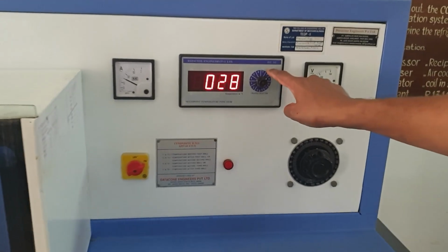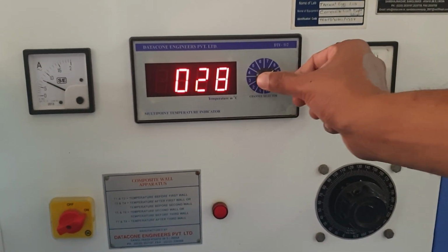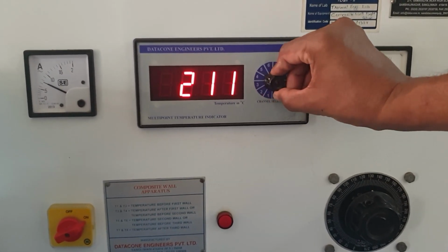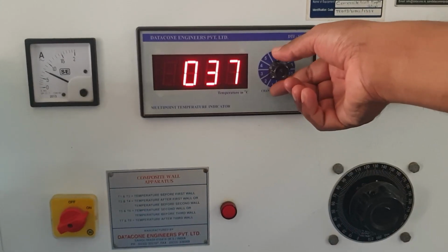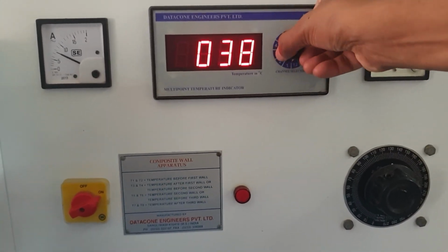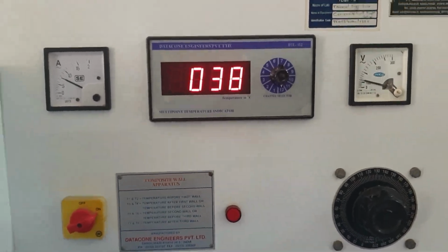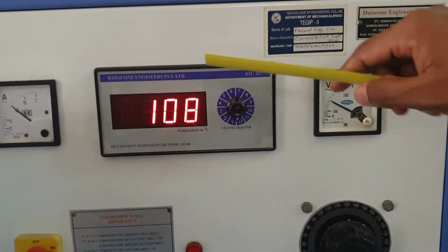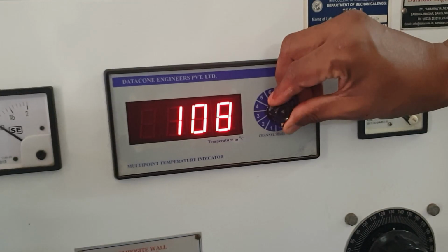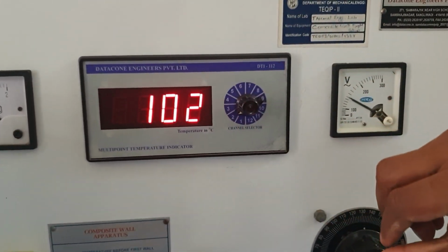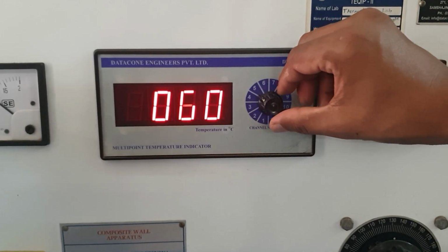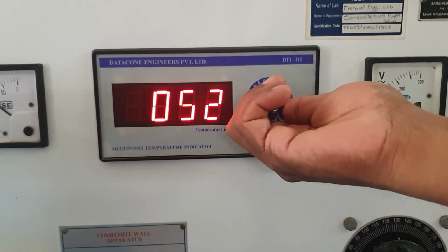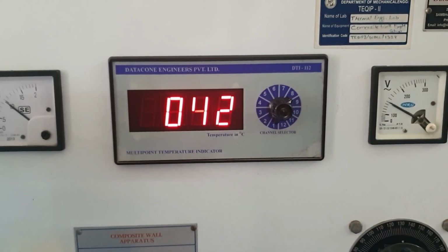Now when we vary the input, the temperatures at different points will vary, because heat will be conducted from the copper through the mild steel, wood, and alum, but the resistance to this heat transfer will be different. It depends upon the surface area, which is actually constant here, the thickness, as well as the conductivity. The thickness values we know here. You can see the temperature varying at different points because of the thermal resistance offered by these materials. The temperatures vary from about 107 or 108 degrees to 42 degrees, depending upon the resistance in each layer.